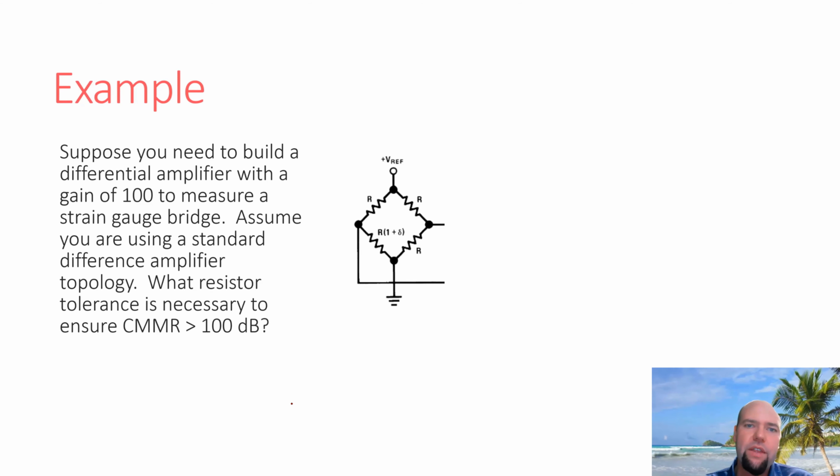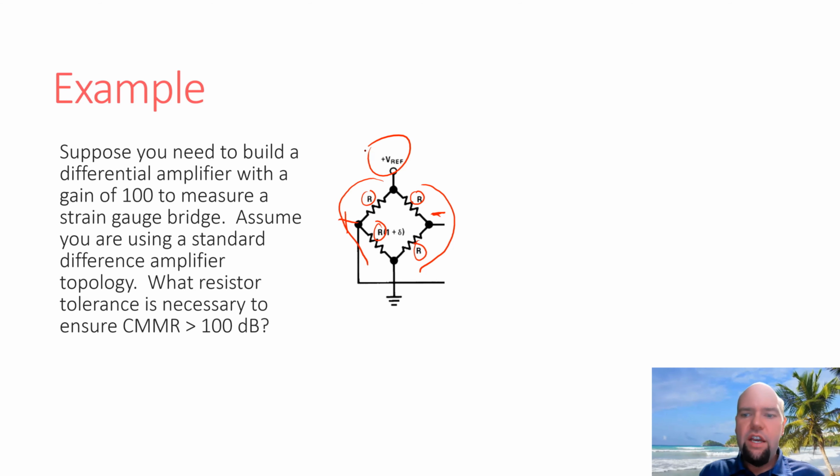And a good way to clean this up is with a bridge. So a bridge circuit, essentially you have two sides of the bridge, which are voltage dividers. And so the ratio of this resistor to this resistor versus this resistor to this resistor creates a differential voltage in the middle of the bridge. And the nice thing about that is that differential voltage highly rejects any noise that comes from your reference voltage. By looking at the difference in a balanced ratio of resistors, this differential signal is basically a way to eliminate supply noise.